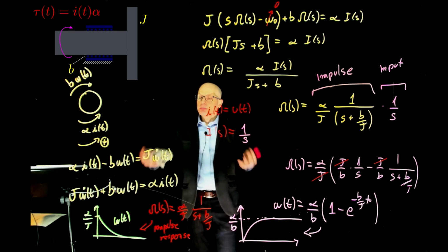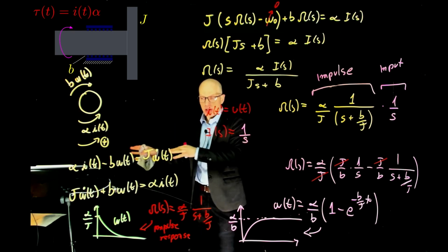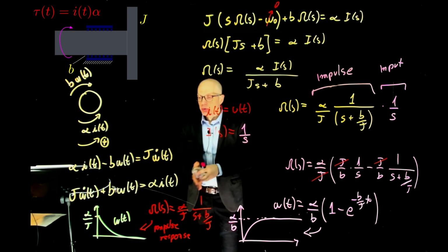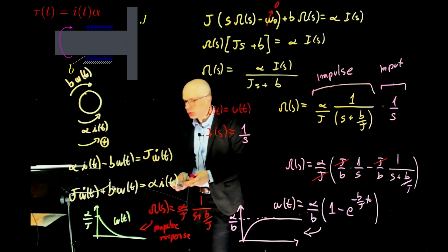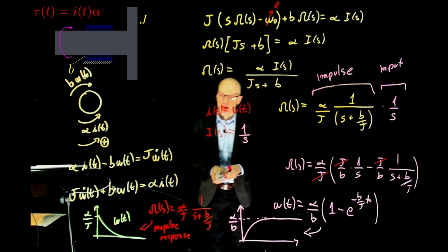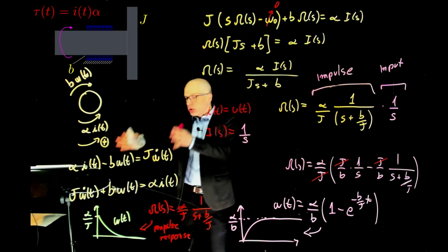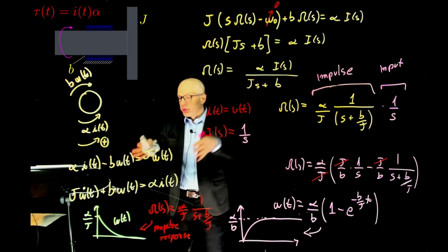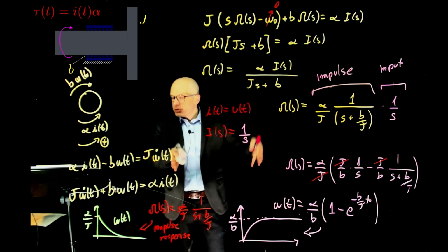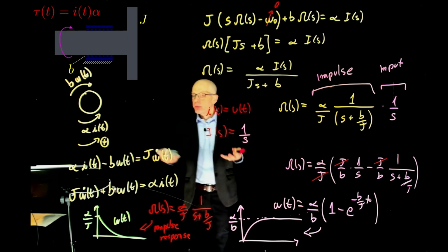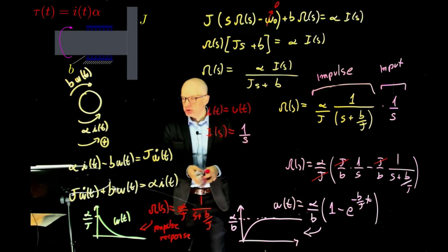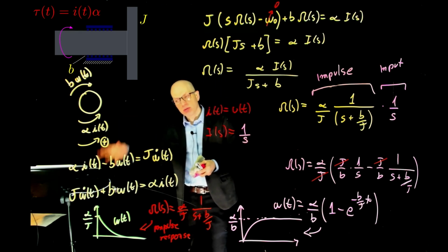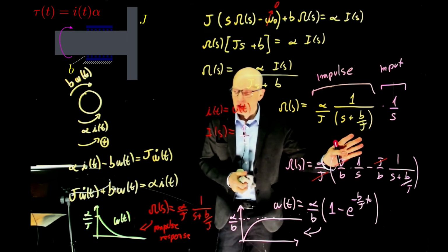We took, by multiplying their Laplace transforms, their convolution. So we took the most elementary way the system can respond to an input, which is its impulse response. We took the convolution of that signal with an input signal, and through that operation, we found the time response of the system for that specific input based on how it responds to an impulse. That's exactly what we did here.